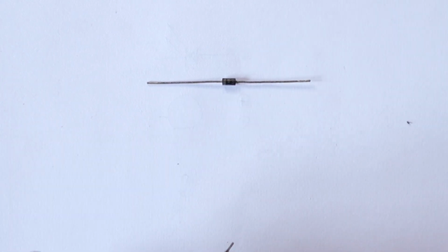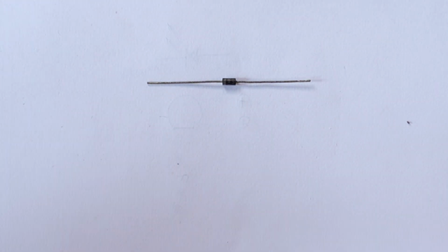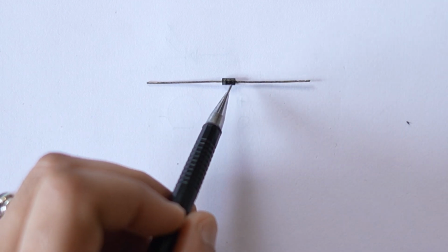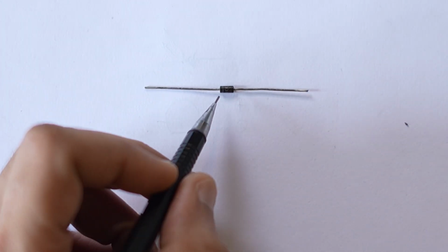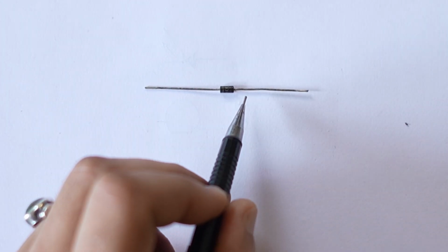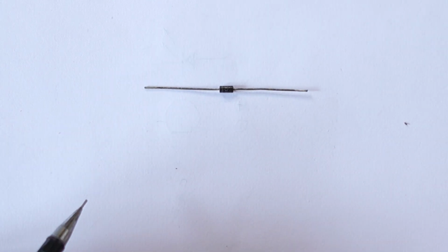And basically a diode, consider it like a valve that works only in one direction. So it lets current flow in one direction but not in the other. It's like a blocking device, which is why they always have a polarity. Most diodes will have a band that indicates what's known as a cathode, and the other end is obviously then the anode. So the higher potential goes on the anode side, and the lower potential comes out on the cathode side.